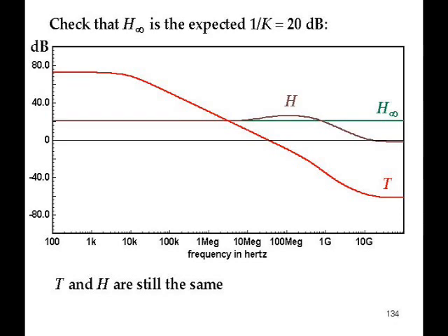Closed loop gain peaks up before falling off. Oh, we don't have enough phase margin. Not true. Phase margin is fine. Loop gain is fine. Where does the peaking in H come from? It comes from the non-idealities. It comes from the H0 or the Tn, whichever one you want to use to represent it.